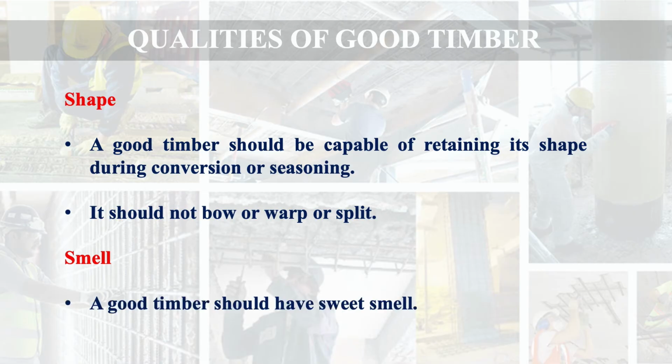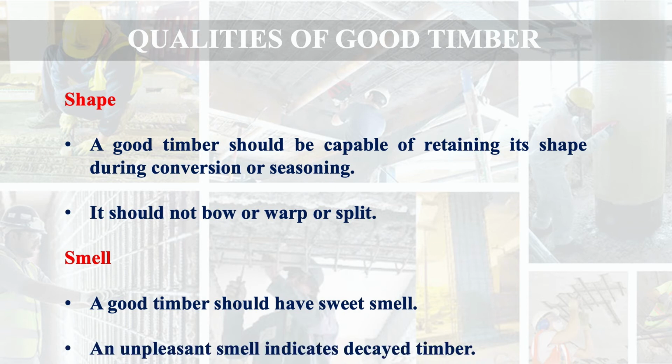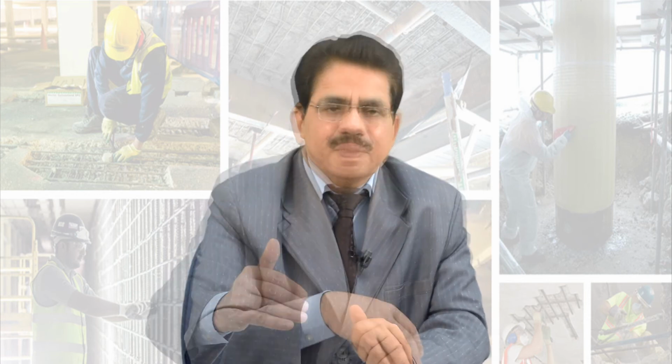Then next quality is smell. A good timber should have sweet smell. Why? Because an unpleasant smell indicates decayed timber. It is not about giving a good fragrance to the room, because the smell is linked with the health of the timber, and unpleasant smell means decayed timber. So a good timber should give sweet smell, not the unpleasant smell.